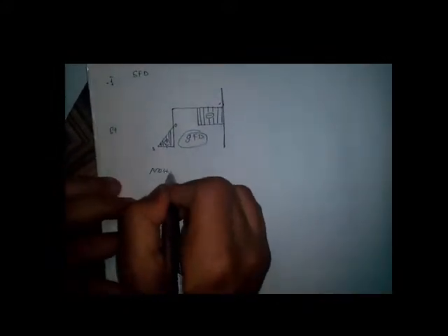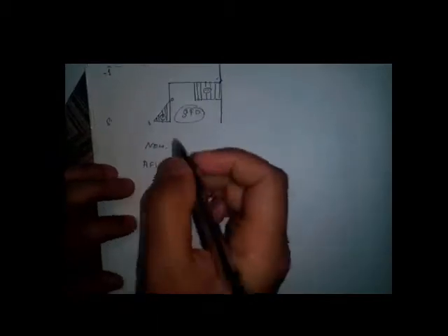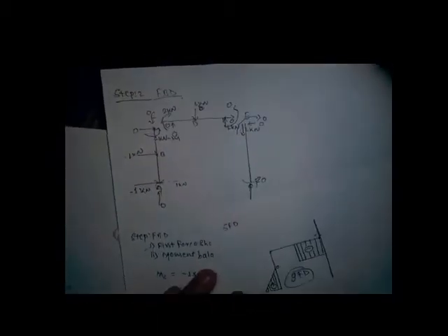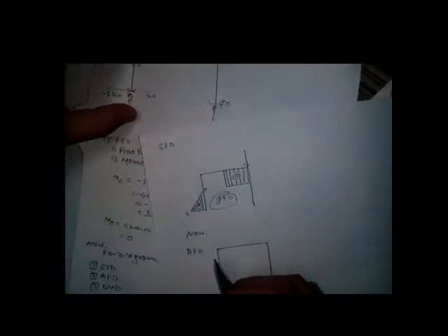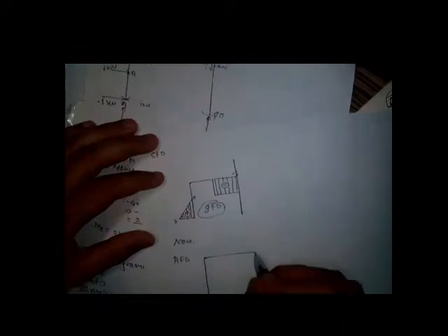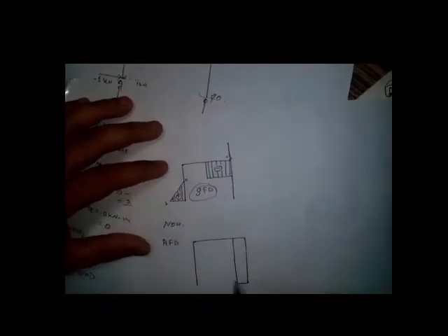Now we go to the axial force diagram. For the axial force diagram, you need to observe the figure. The axial force diagram shows a compressive force or tensile force. You can see here 0, 0 compressive force. That means it is compressing the member. So here it is 0, 0. No need to mention. At this point also you get 0, 0. That is a tensile member, and it's 0, 0. So there's no need to mention it. Here is 1 kilonewton, and here is 1 kilonewton. That is a compressive member, 1 kilonewton. So it will be drawn like this, and as a compressive member it's negative, with hatching perpendicular to the axis.